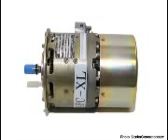By replacing the slip rings of the basic AC generator with two half cylinders, called a commutator, the basic DC generator, Figure 9.6, is obtained. In this illustration, the black side of the coil is connected to the black segment and the white side of the coil to the white segment. The segments are insulated from each other.